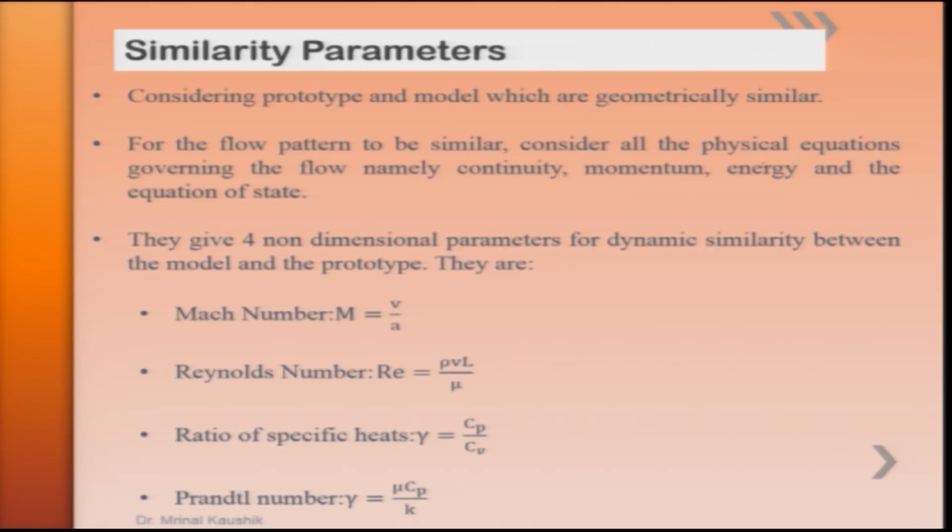In these circumstances, assume that both the model as well as the prototype are geometrically similar. Under this condition, the flow patterns are similar, considering all the physical governing equations, that is the continuity equation, momentum equation, energy equation and equation of state.